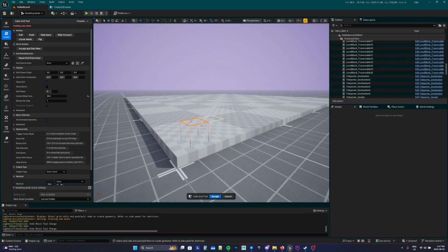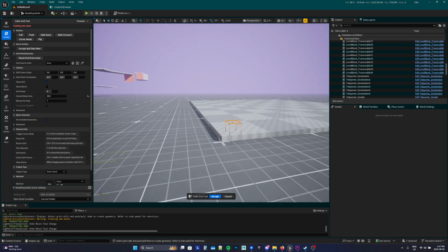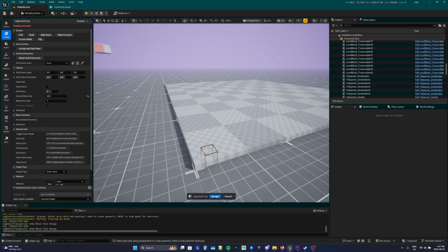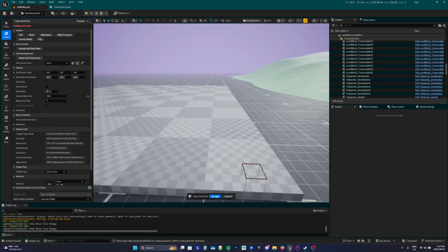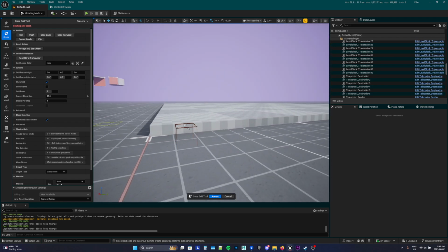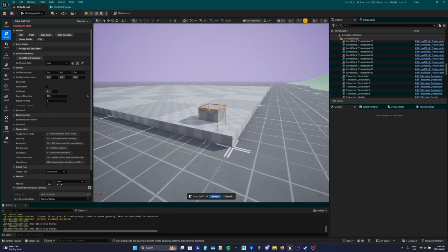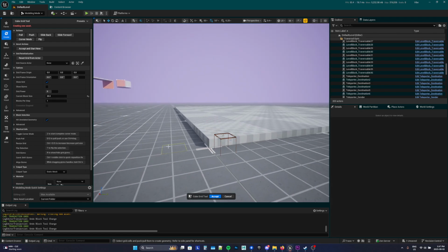So there's a couple things you can do. You can hold Shift. See if I can find, maybe it doesn't tell you about Shift. So if I hold Shift and Q, Shift and Q will just move my grid up and down without pushing or pulling geometry. So this is a way I could do it, is set my thing underneath and then create my new geometry from that.